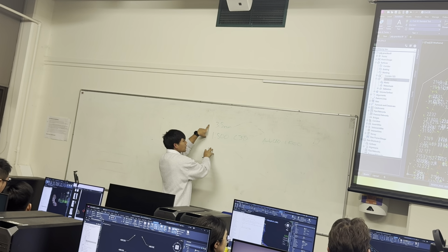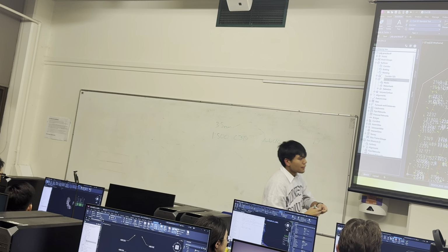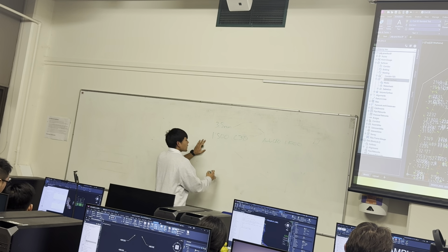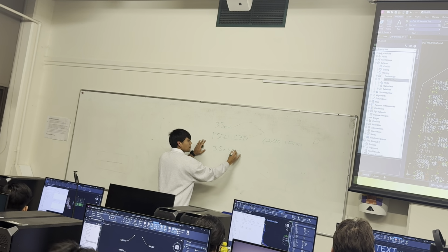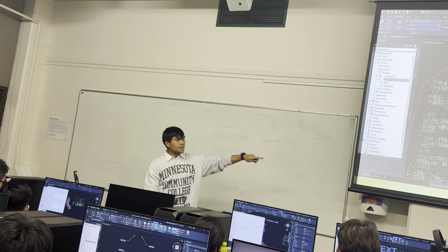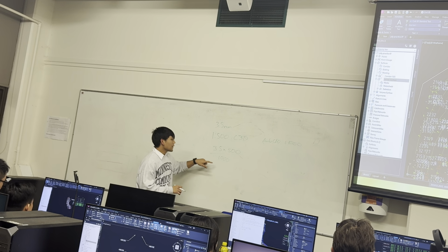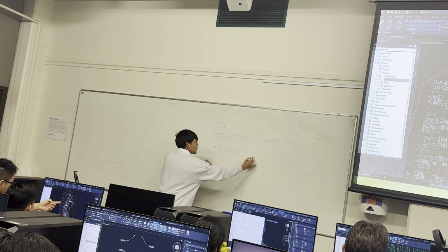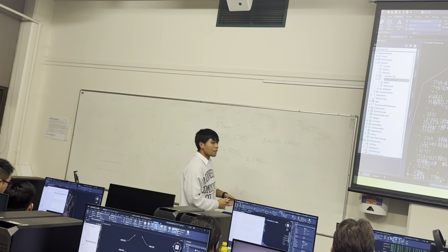So if our scale is 1 to 500, you can see here it's 1 to 500 by standard. So what we'll do is we will times that 3.5 by 500, because that's our scale, divided by 1000, because these Autodesk products, Civil 3D and AutoCAD, will be in meters. That's why we divided by 1000. That should give us 1.75. So just use 1.75 for your label.